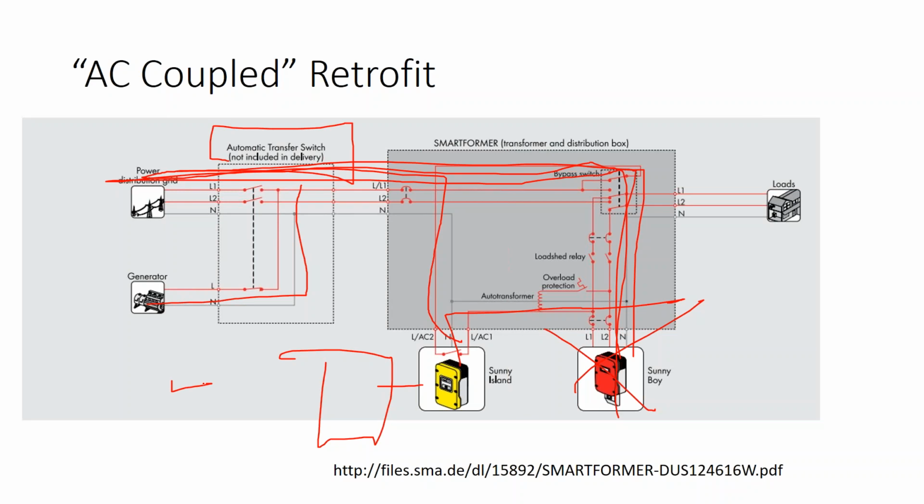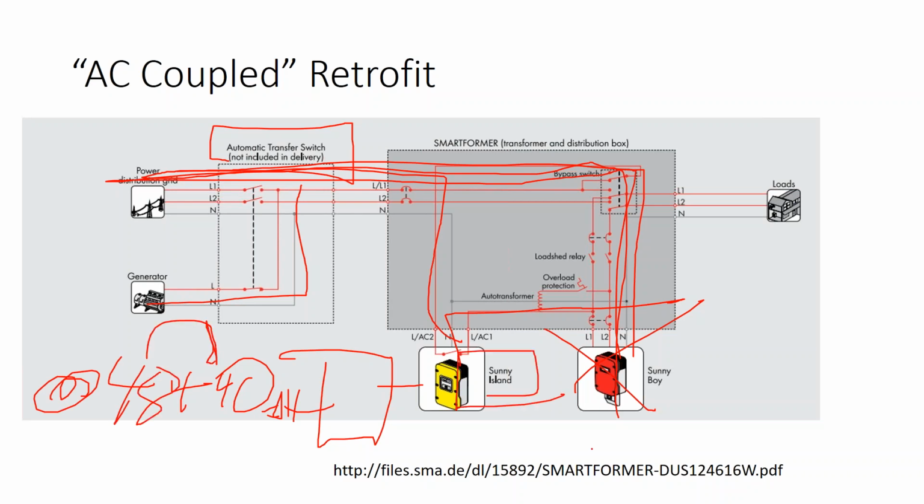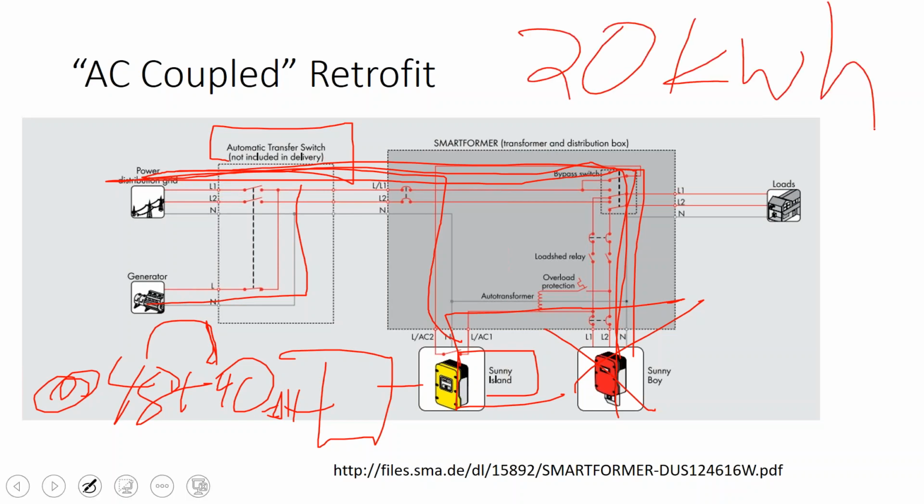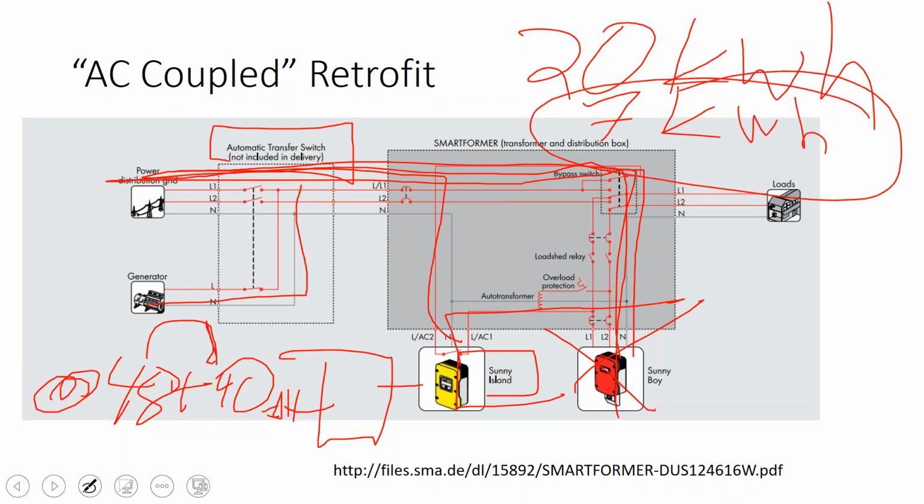And these batteries only need to be about 440 amp hours at 48 volts, and that's for a situation where the battery inverter is not designed to fit with the battery chemistry. And so 48 times 440, you're looking at about a 20 kilowatt hour battery bank at the residential level using the traditional methods of battery inverters. And then the Tesla Powerwall is only about 7 kilowatt hours, so it's substantially cheaper.